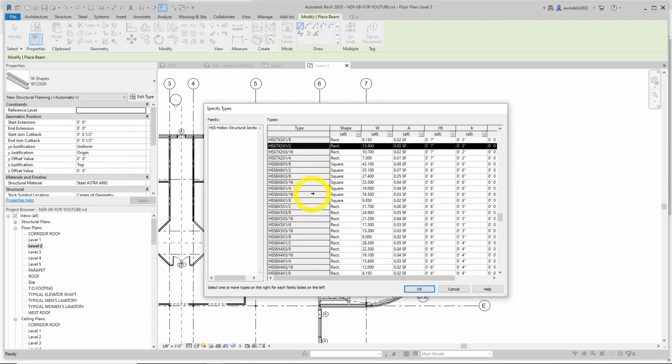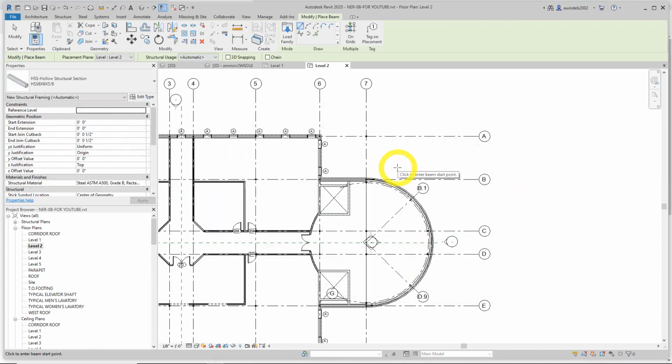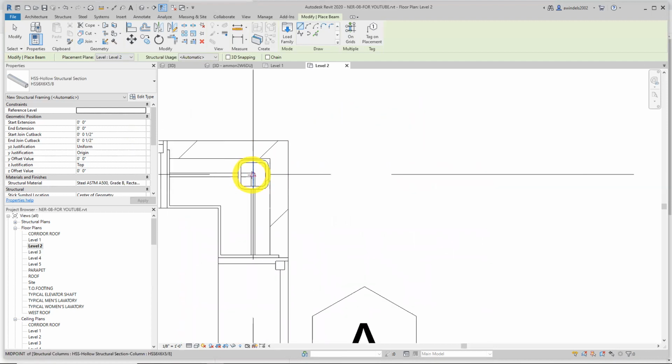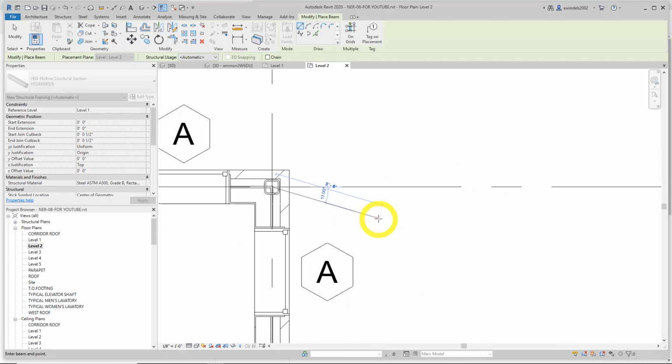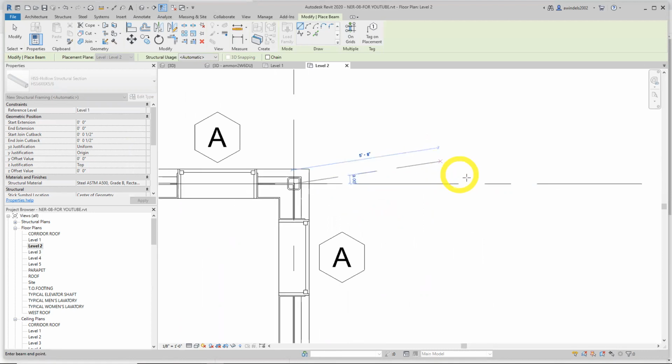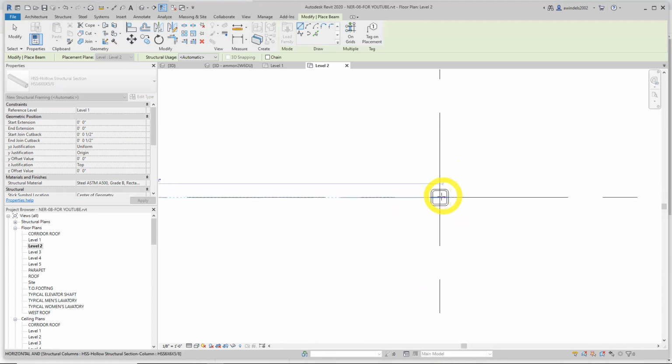Matching our columns somewhat for design. On to page 394, very surgically, we'll pick points 1 and 2 between columns A6 and A7. Okay. And we'll do midpoints. I'll go slow on this one. Right here. Making sure my options were selected correctly. I believe they were. We can double check in 3D view, which is always good.